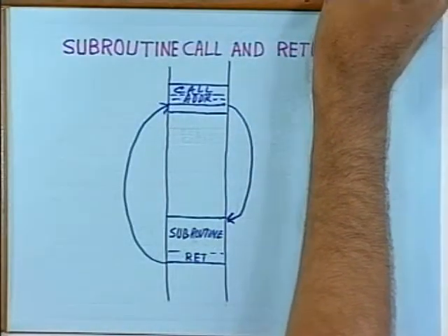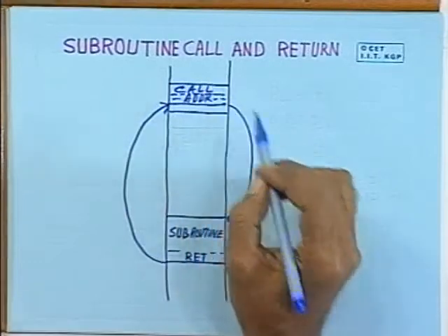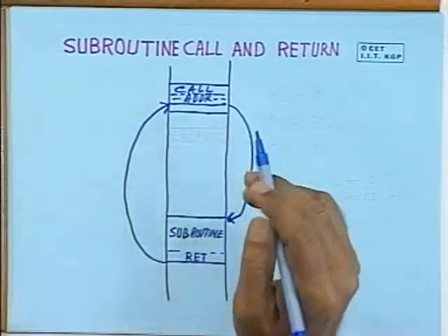Now, whenever you are calling a subroutine, although the program counter is being stored in the stack, apart from the program counter, you may be using some registers. Some registers may be holding some useful intermediate data, which you will require after you return from the subroutine. Those registers may get modified if you don't save them in the stack.